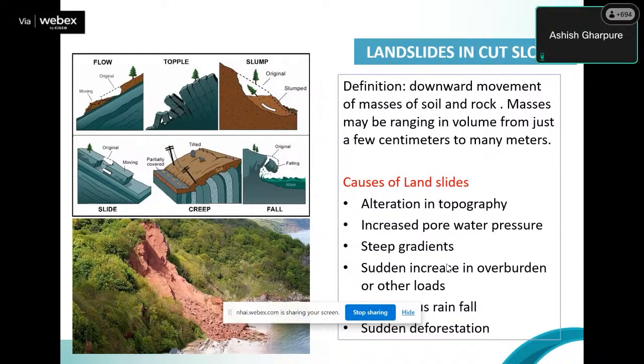Then there are toppling of rock, overall slump, classic slip failure, as well as slide of one rock layer on top of other rock strata underneath. Then there is creep, very gradual movement, where mostly this is clay soil, conglomerate type of material, where you can see everything tilting and moving very gradually. It may not come down in one go, but it may keep on increasing till a point where you can see the failure. And there are topplings and overhangs failing and so on.